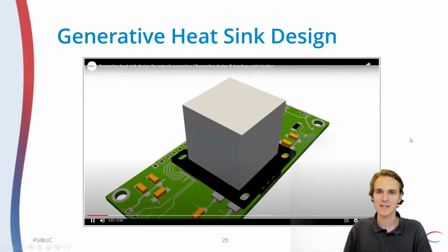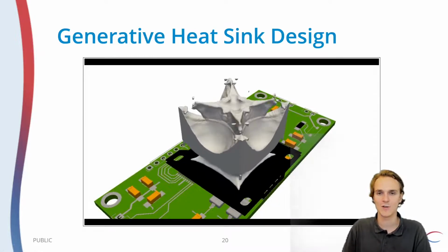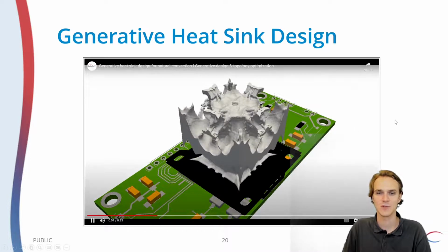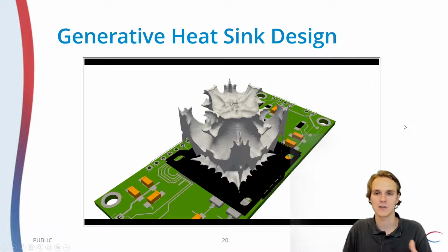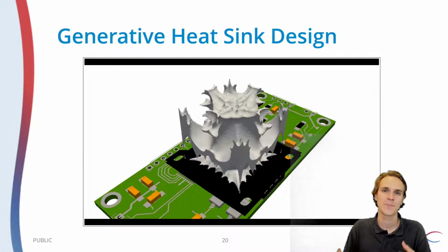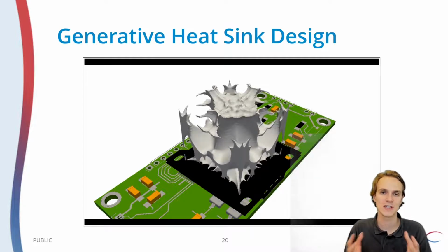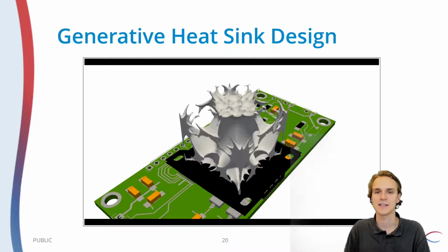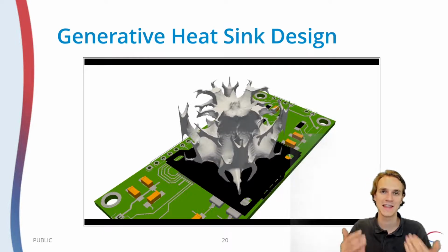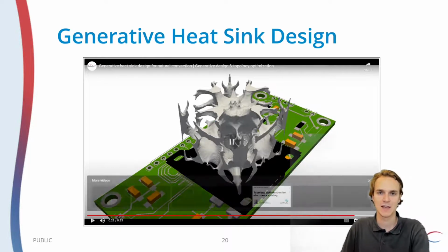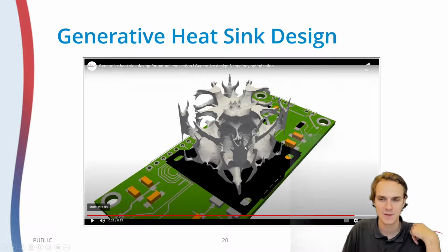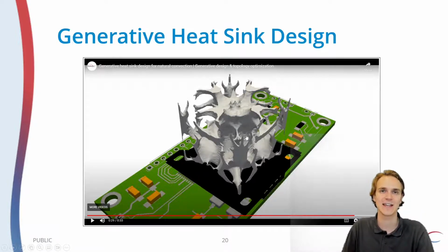So you see the heat sources are located on the bottom, and already you see ColdStream in action doing its generative design for conjugate heat transfer. And what's novel about ColdStream is that it combines both flow and thermal boundary conditions into one subset and does topology optimization to address the needs for both of those requirements. And so here you can see quite nicely a quite final iteration of a heatsink that you can expect when you use ColdStream for generative design.